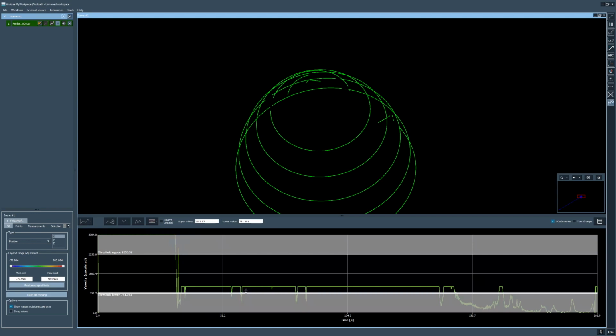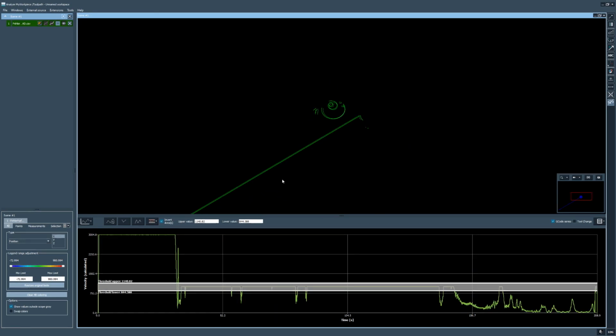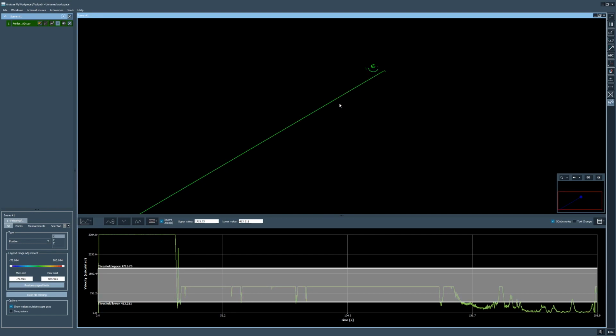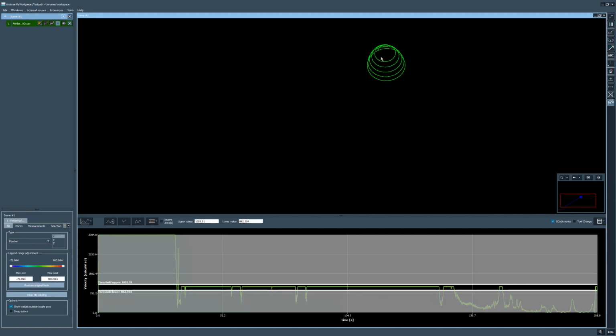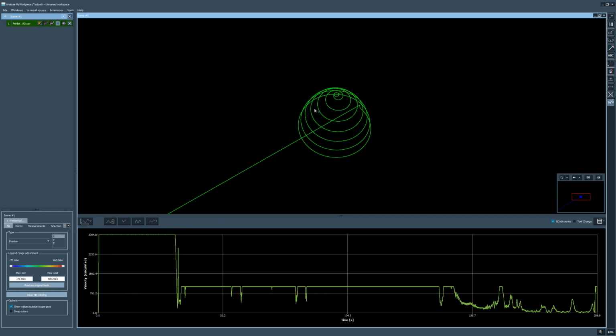It also works with double threshold, so if you want to look at a specific, very close area, like show me everything that is outside between those two values, I can invert it. So now we see the areas where the tool is either very slow or very fast. That's why we see this line here again. Or you can make it like that, then you see everything that is in between. So the thresholds are also very important to find areas where certain boundary conditions are set or met. This you can switch off. We're using no thresholds, and then you are on the original view again.